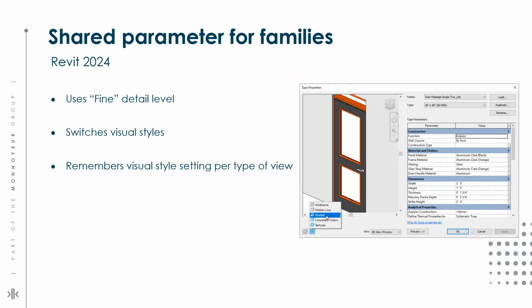So we do have this shared parameter, which I told you, which is with respect to the families. In terms of families, we have a shared parameter where there are two different types of families: a type family, which can't be editable, and an instance family, which can be editable at any period of time in a particular project. Likewise, if a door is there, it has certain parameters associated with it, for example width, length, height, depth, thickness. When all those parameters are brought onto a file, they would be visible and editable, and you can make the changes according to you.